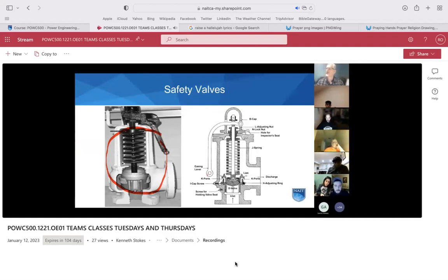Some common features of most safety valves: a tri-lever or an easing lever, something that you can grab onto and pull. This is actually a device that allows you to open the valve. Pull up on the stem. The stem is in the middle, in the center of a large spring or a small spring; small boilers have small safeties. Internally, there's a disc and a seat.